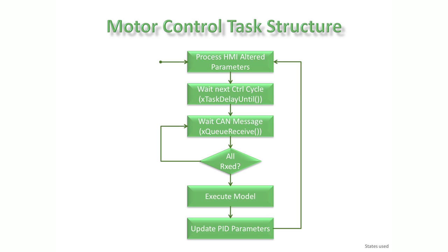Here is a FreeRTOS API function which is used to create a periodic task. Just to explain this a little bit, the X denotes the return type. Task tells you where that function is defined, so in this case, it's in tasks.c. And delay until is quite a verbose way of telling you what the function does. FreeRTOS tends to have very verbose function names, which some people really like and some people really hate. But I don't like cryptic acronyms myself.